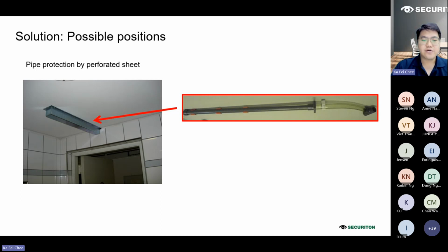And of course, conventional detectors are usually less sensitive. For the ASD system, we are able to set the sensitivity from class B to class A and above, so that we can have multiple levels of fire alarm, like pre-alarm 1, 2, or 3, to gain extra time for the staggered or sequential evacuation procedure if there is a fire.